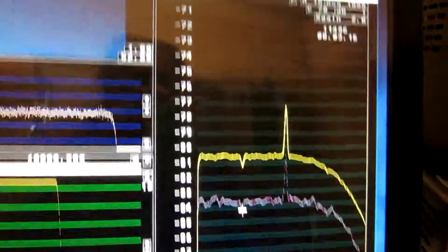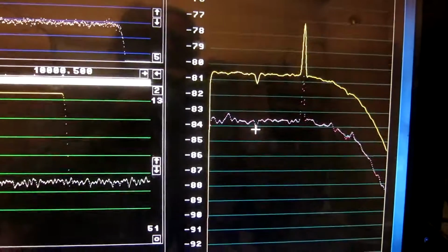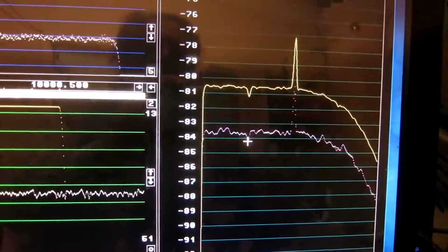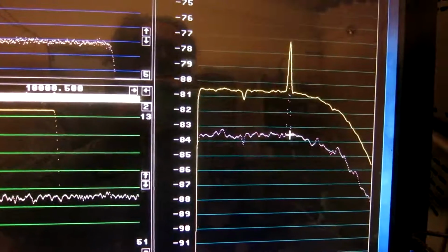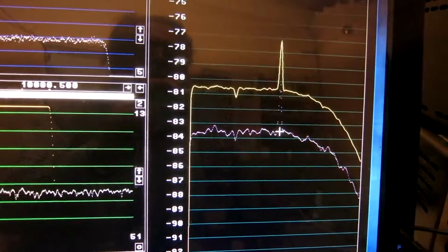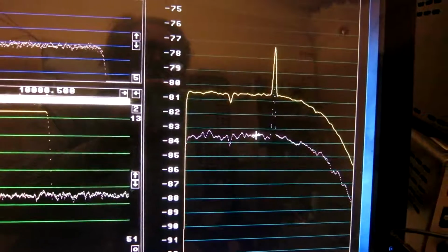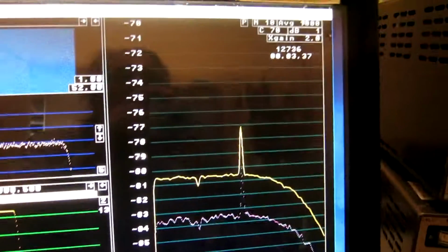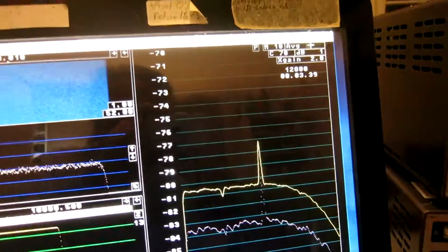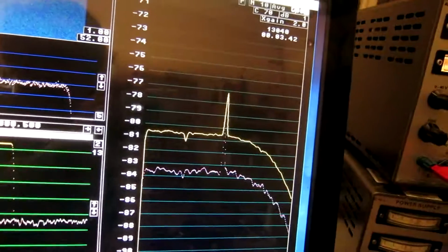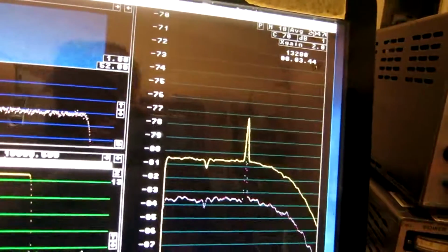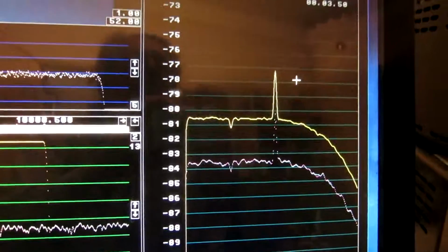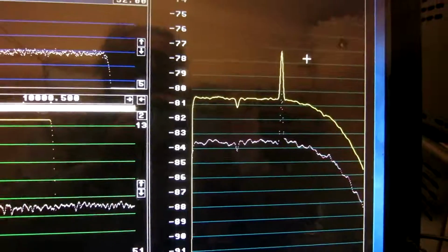This notch is at about 700 Hz. It's DC from my direct conversion receivers. Here is the mirror image. Why the floor is not perfectly flat here, I don't know. Maybe I can use more averaging. I don't remember how far I can go with this. 2047. So I have to wait until it has actually collected that.